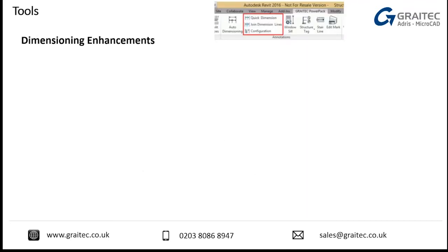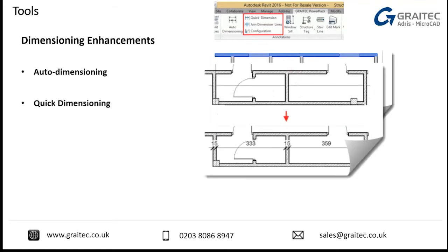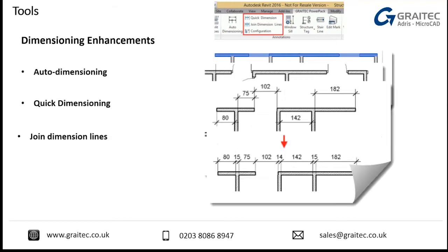It's very clever. We've got some dimensioning enhancements. Dimensioning is very, very good and very powerful in Revit, and there are some nice features for doing it quickly. We've just given you a load more tools to do it even faster. So we've got an auto dimensioning tool where we can select an object and it will auto dimension objects. We've got a quick dimension tool which takes a line, where we can draw a model line directly through objects. Every object that touches it will then start to dimension for us.